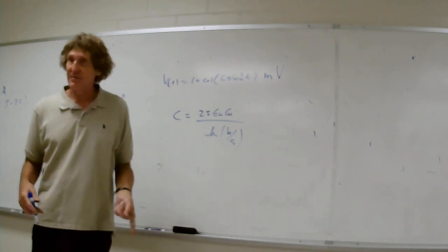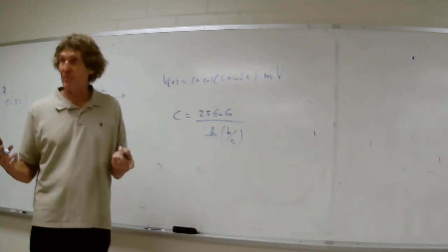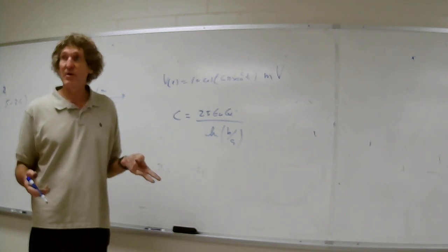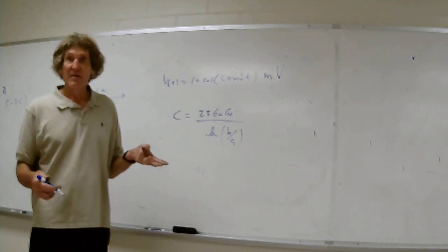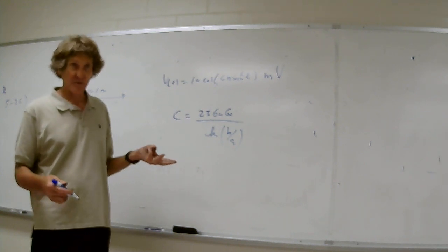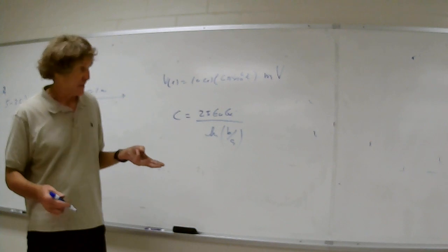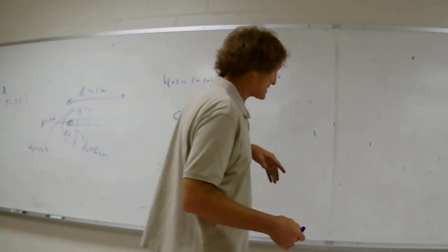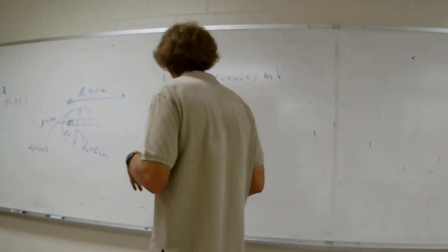You assume a charge, then you find the D field, charge over 2 pi rho. Then you find the E field, dividing by epsilon. Then you find the voltage by integrating. Then Q over V is C, and this is what it comes down to. Now they want the current. If that's the capacitance, how do you get the current?